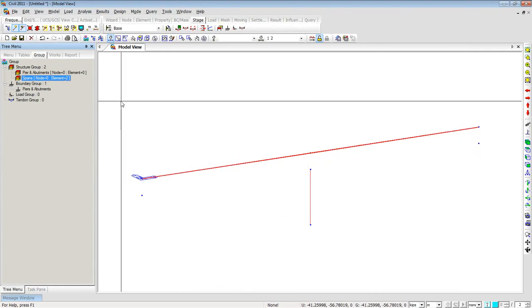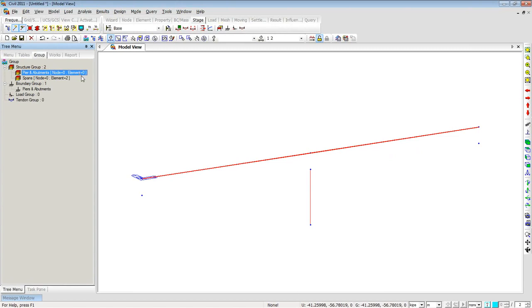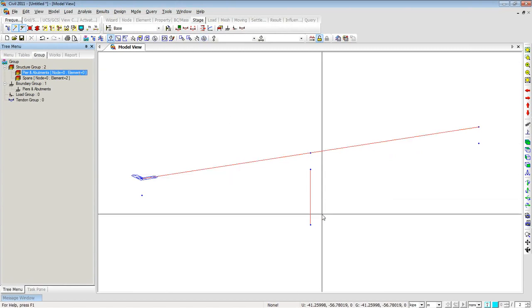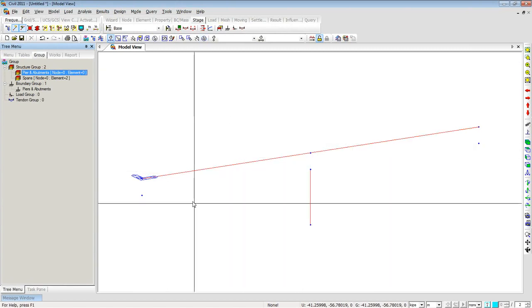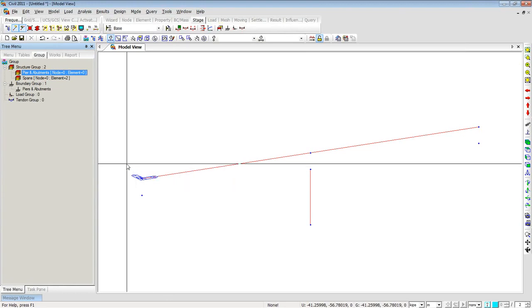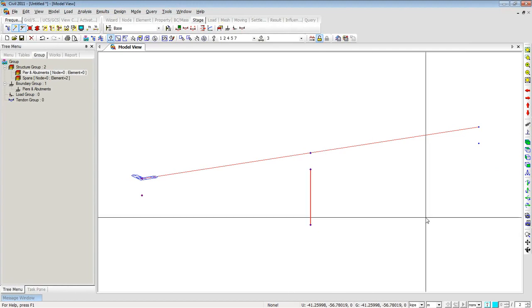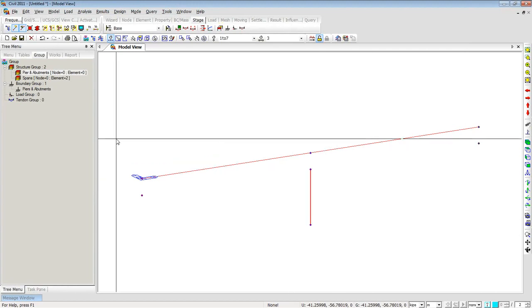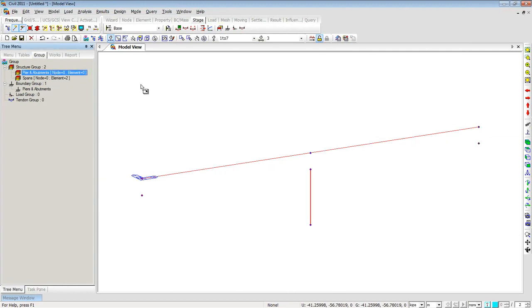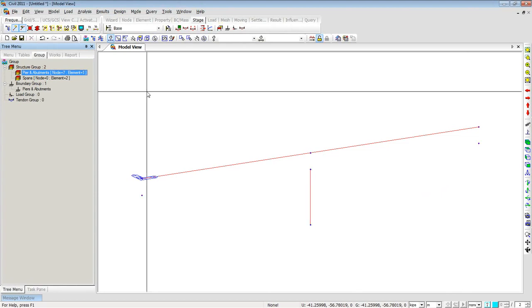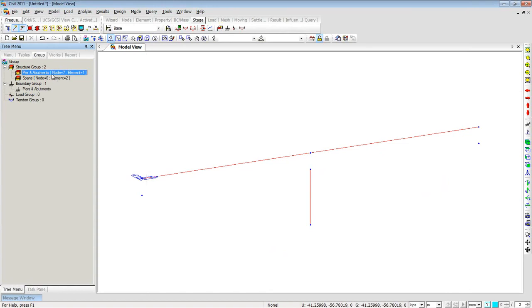the element selected. And since I'm activating the pier assembly and the abutments in first construction stage, so I'll select the nodes that are corresponding to piers and abutments and put them under the pier and abutment structure group. Now having done this, I'm ready to define the loading data onto the structure.